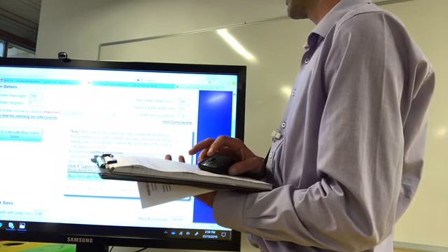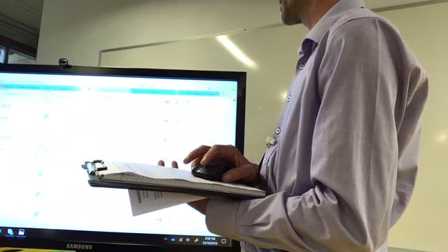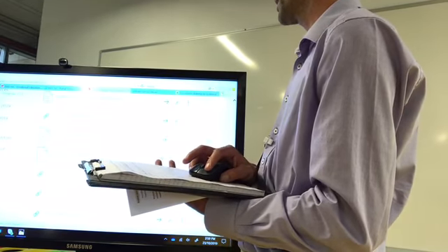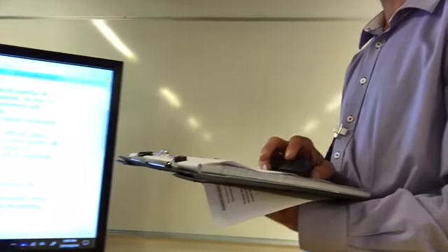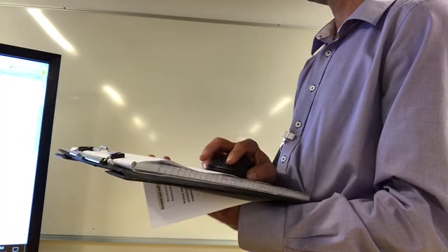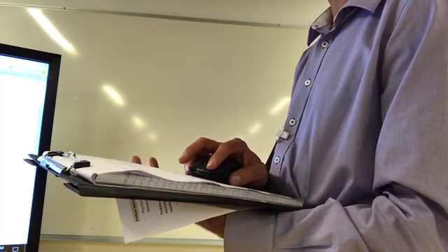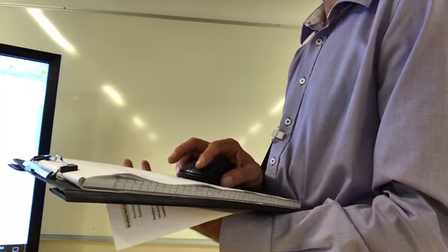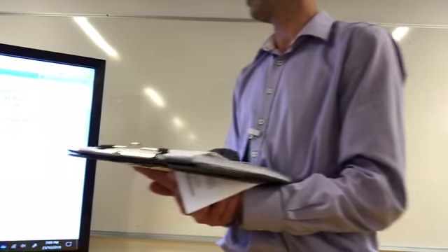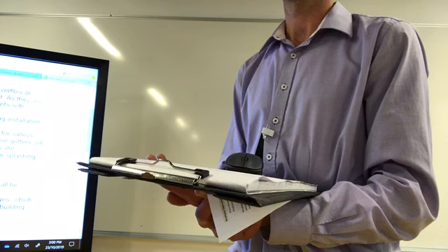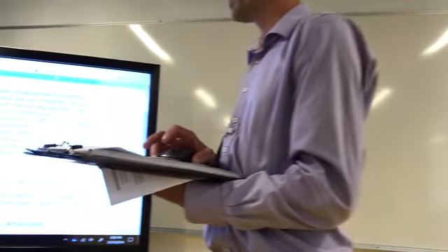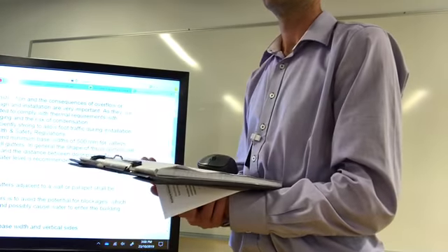So if we go back to the Learn page and have a look in the box gutter information, industry guides to good practice recommend minimum base widths of 500 millimetres for valleys and 300 millimetres for parapet and boundary wall gutters. So we're trying to get the smallest one in there we can. You can increase that if you wish.